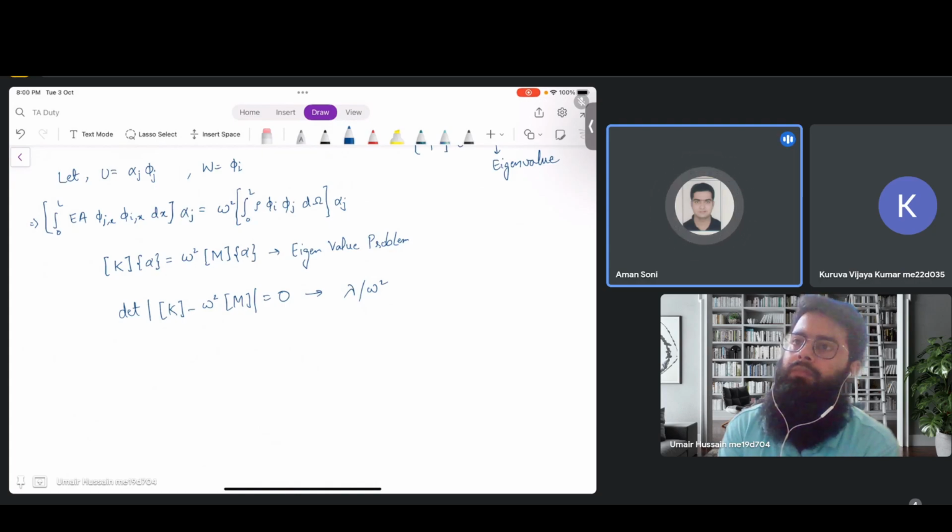I didn't get how it is defining the mode shapes and the displacement values for a particular mode shape. For example, whether there is a shear mode, a torsional mode or a bending mode, how is it deciding, because load is completely absent there? To limit the displacement value we have to define some load, because we have the stiffness matrix, and to define this alpha we need something in our hand. So how is it deciding?